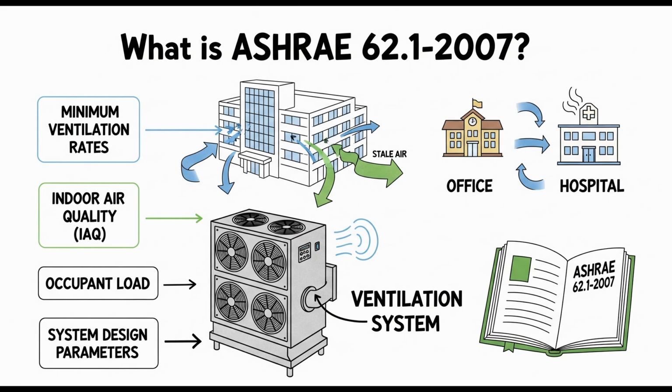Seems thorough. What happens if during maintenance you actually find mold or standing water? Sections 8.4.2 and 8.4.3 are very direct. Visible microbial growth or significant water accumulation found anywhere in the system must be investigated and remediated promptly. You can't just ignore it. It ties right back to those material requirements and drain pan tests. Find it, fix it.